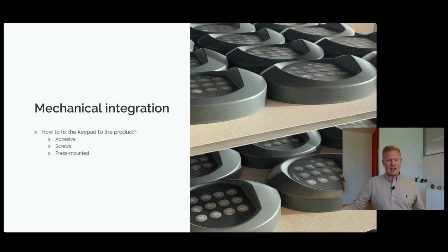So the first thing you can ask yourself is, how is the keypad going to be fixed? Are you going to use adhesive? Do you need screws? Is it press mounted or something else? And when it comes to the adhesive, the assembly surface is very important. It's important to have this spec early to choose the right adhesive material. And that's a huge area with adhesives, so that could have a whole separate seminar for itself.